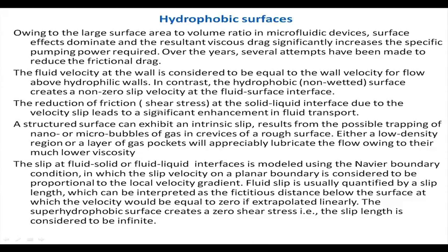If we have a reduction in the friction or shear stress at the solid liquid interface due to the velocity slip, we get an enhancement in fluid transport, because the momentum loss due to friction will be reduced. These things are very applicable in fluid transport, pressure driven flow and all.